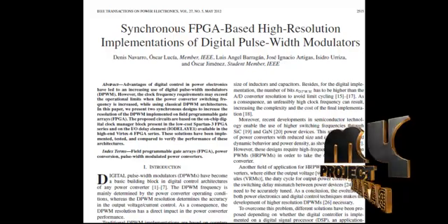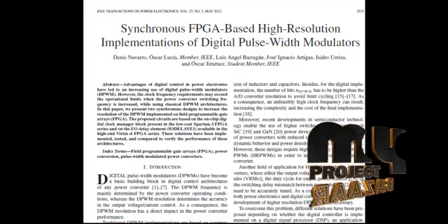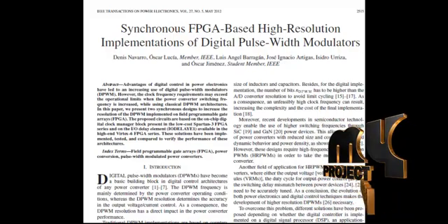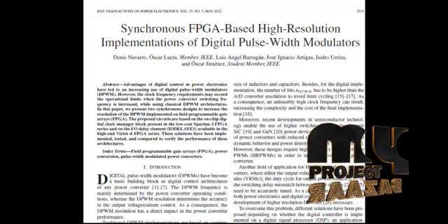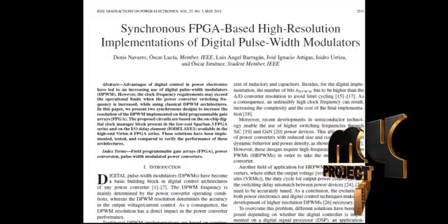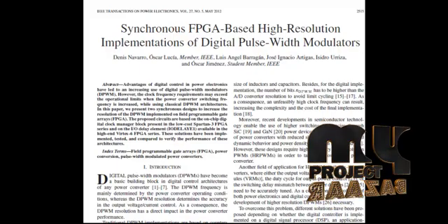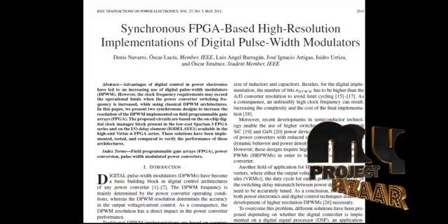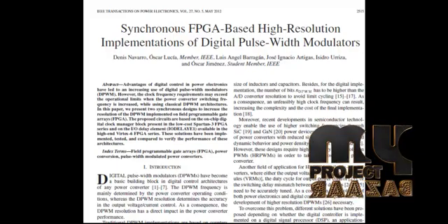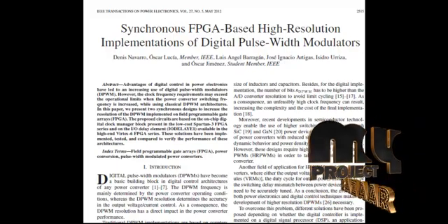Almost every FPGA includes a DLL block with phase shifting features. Taking advantage of this resource, the proposed architecture obtains excellent conditions. The proposed digital pulse width modulator is in principle independent of the FPGA implementation, and an integrated circuit implementation would need the development of a DLL with phase shifting capability, which is the most complex part of the architecture.